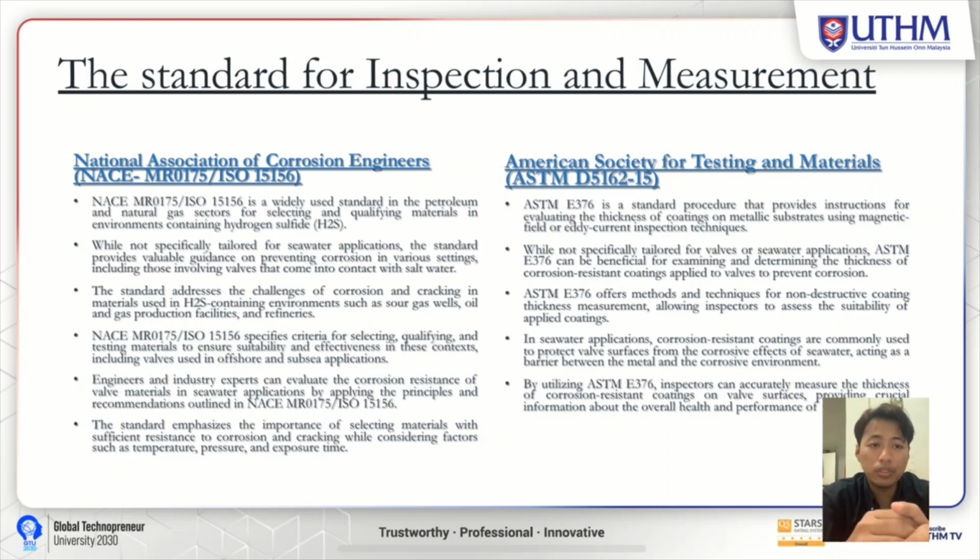The method is used in H2S-containing environments such as sour gas wells, oil and gas production facilities, and refineries. Engineers and industry experts can also evaluate the corrosion resistance of valve materials in seawater applications by applying the principles and recommendations outlined in NACE MR0175. The standard emphasizes the importance of selecting materials and specifying resistance to corrosion and cracking while considering factors such as temperature, pressure, and exposure time.